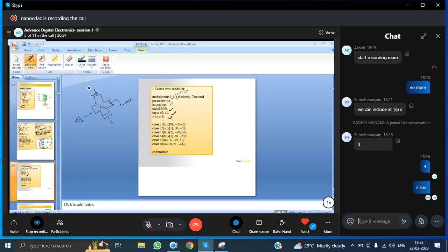Here you have C0 and the negation of C0, like that. One more CMOS which you need to take, like that. 1 2 3 4 5 6, CMOS switches you are taking. So 4 CMOS switches are for the 2/1 mux implementation. These are for generating the output.